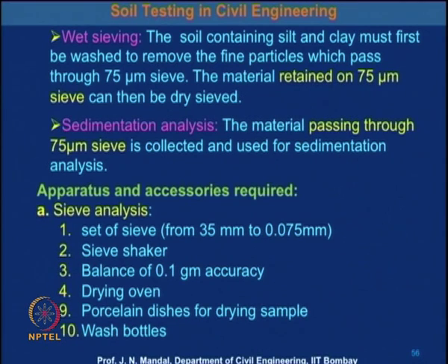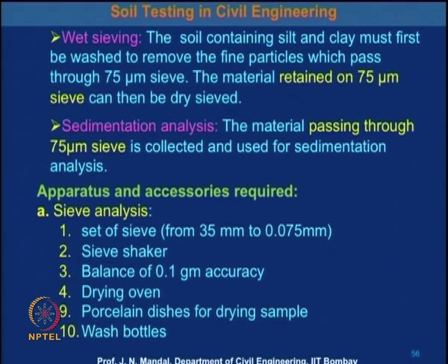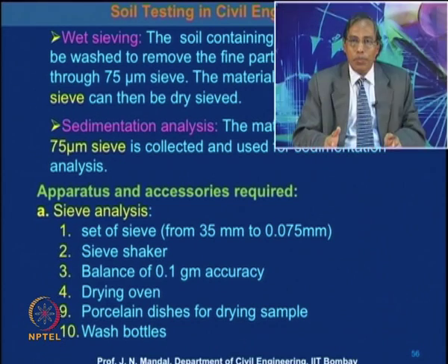Thirdly, sedimentation analysis. In case of sedimentation analysis, the material passing through the 75 micron sieve is collected and used for sedimentation analysis. Now, for these different types of analysis, we require different apparatus and accessories.